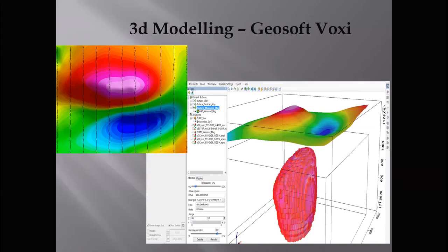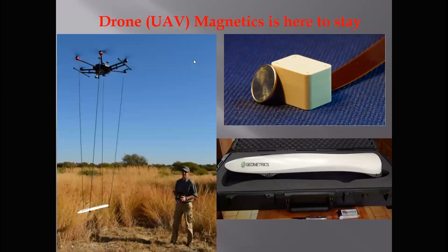We don't know anything about the size or the depth of the body at the time we're usually working with it. So we have to decide what magnetic susceptibility level to clip in the voxel. And depending on what level you clip it at, you either have a bigger body that's shallower or you have a smaller body that's deeper. And that is always the conundrum with geophysics. So that's just to brush you up again on magnetic stuff, so we can move on to the drones themselves.